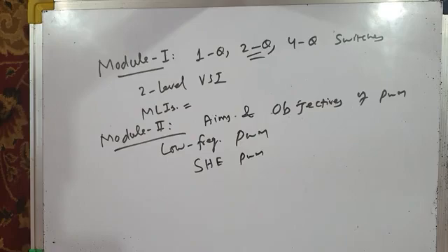We have seen how we can calculate switching angles. If you use two switching angles, you will be able to eliminate one particular harmonic, say fifth harmonic. If you select three switching angles, you will be able to eliminate two harmonics, and so on.